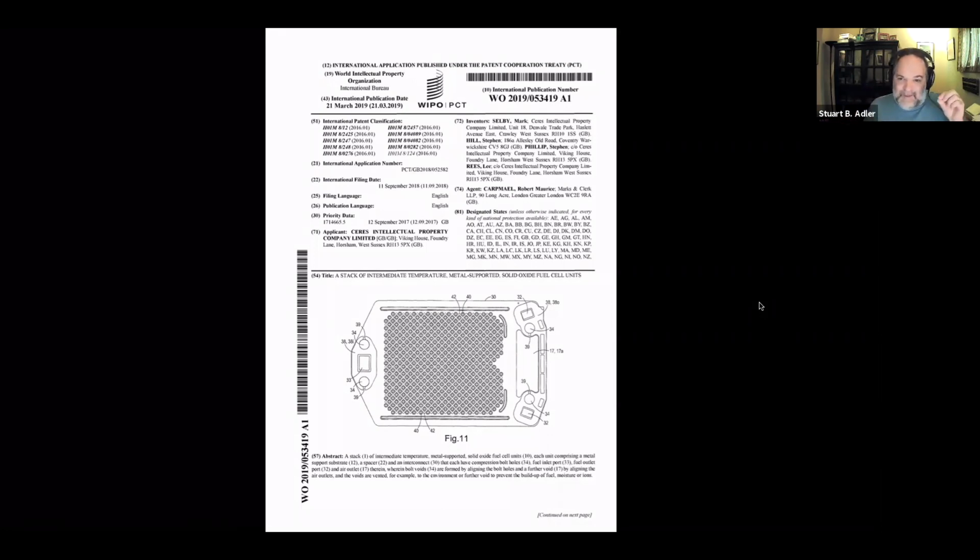The thickness of that cell is just tiny. The actual thickness of the electrolyte, I think, is like 4 microns. It's very, very thin. Of course, that's good because we want to limit the ohmic resistance. What's great about things that are thin is they're actually flexible. Even though ceramics are super brittle, you could just take it and flex it like that. It's like flexing a piece of thin aluminum or something, and that's because it's so thin that you can actually handle the radius of curvature. It doesn't cause too much stress.